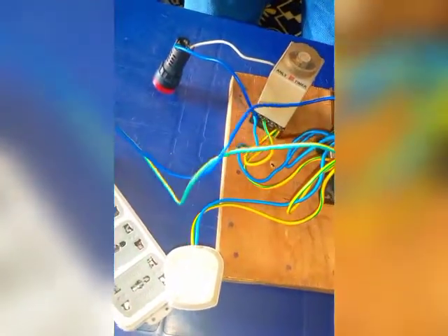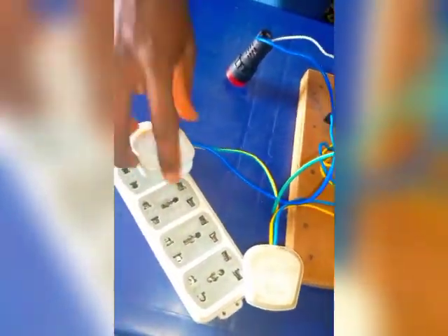Now I will first of all power the generator. When you power the generator, you see that the generator is on. Then immediately NEPA, which means the utility, comes in, the alarm will indicate, and with the help of the timer, this time I have to turn off this alarm. So now the generator is on, and when utility brings light, you see that the alarm will indicate that there is utility. And the timer cuts it off. You don't even notice it. So now even if you remove your generator, nothing happens because utility has taken over.